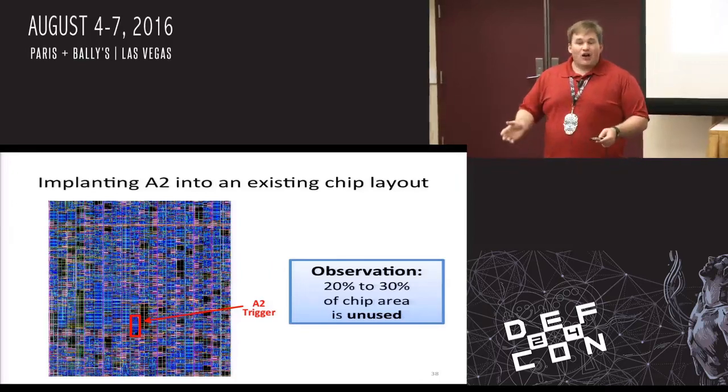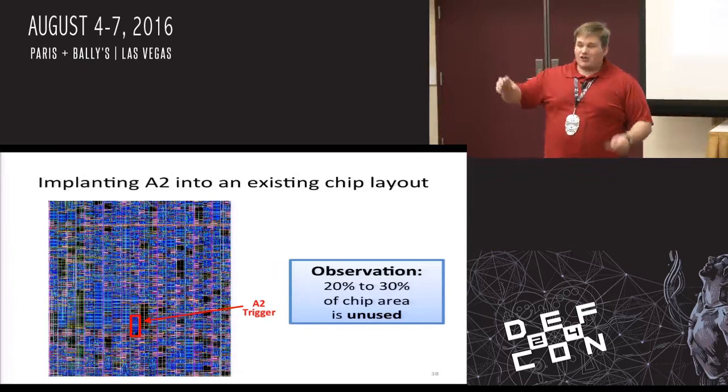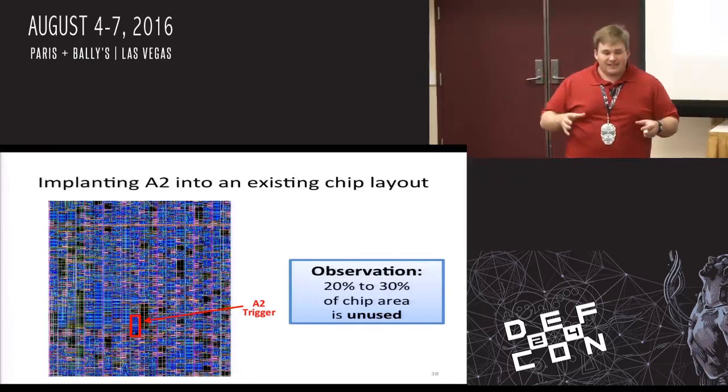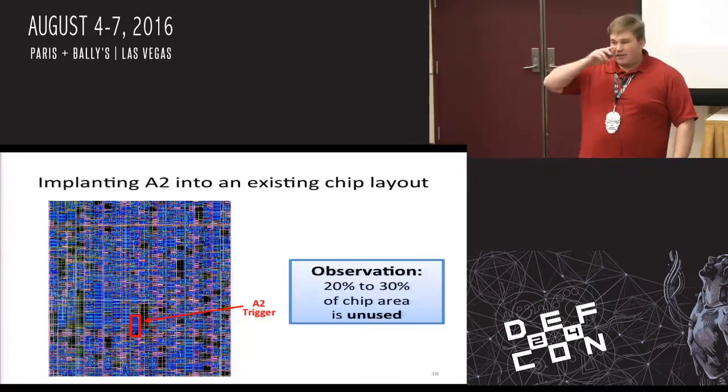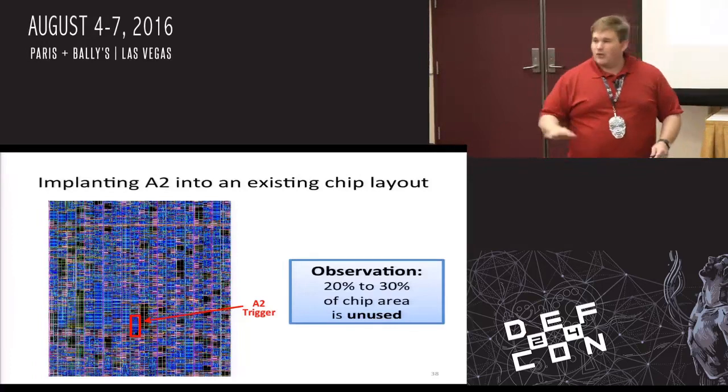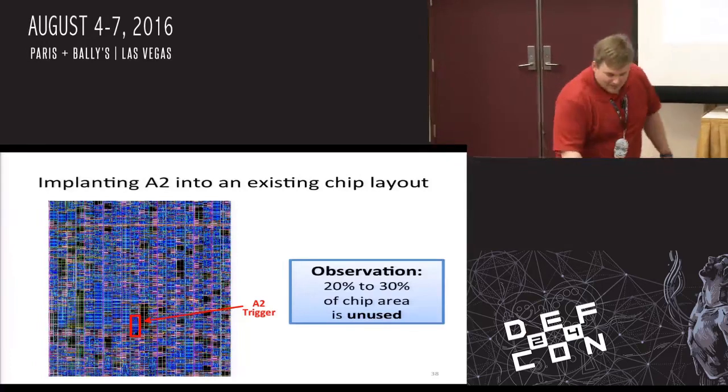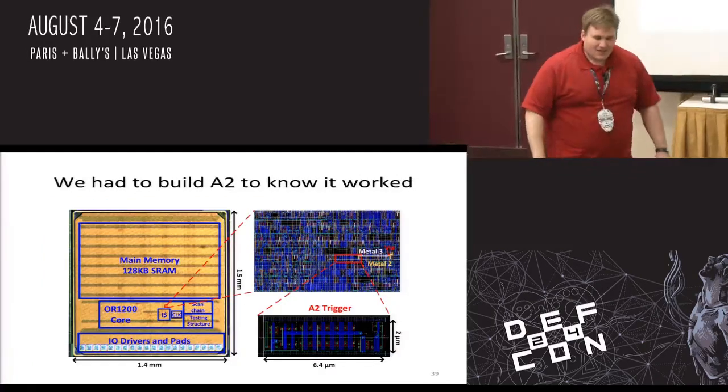Because routing is a very hard problem. It gets exponentially harder the more utilization you have, the tighter your area is packed with devices. So they keep the utilization fairly low, below the elbow of the curve, to make it tractable for tools to automatically lay out your design. So that wasn't actually a problem for us.